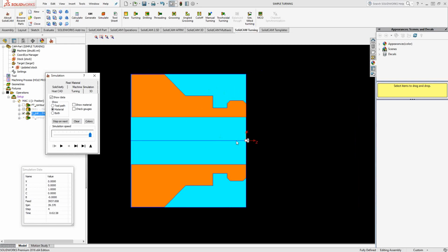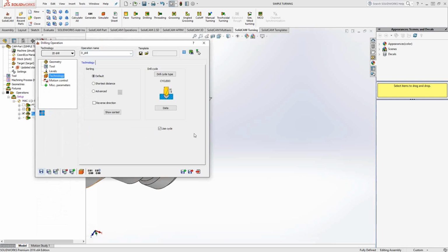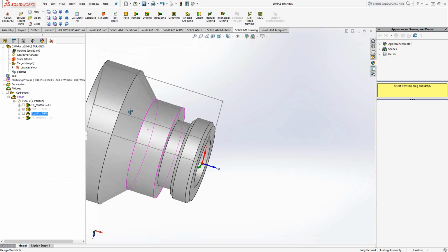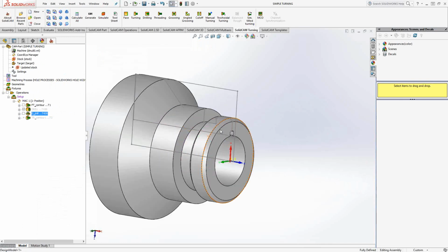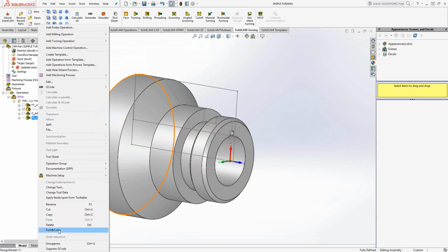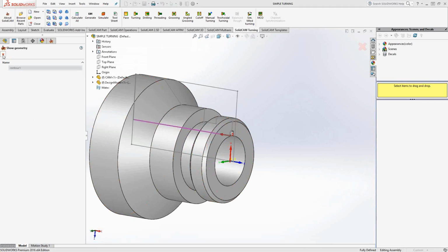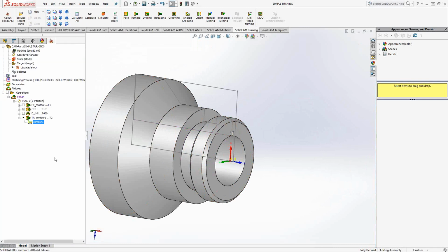So even though the drill went right down the center, and we saw in Solid Verify, it showed everything, the turning and the milling, nothing showed there. And we'll see the effect of something like that. So the drill definitely went down the center, but the updated stock of the turning didn't show anything. So if I bring up a turning toolpath, so this one is actually, if I show the contour, the inside contour. This is the boring operation.